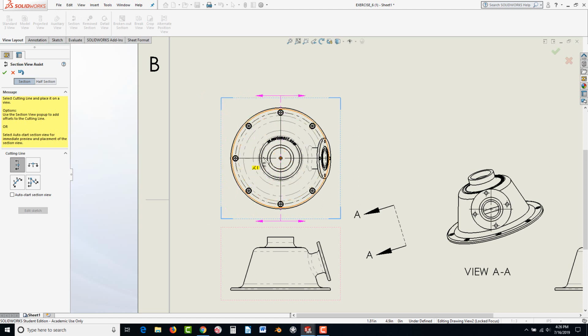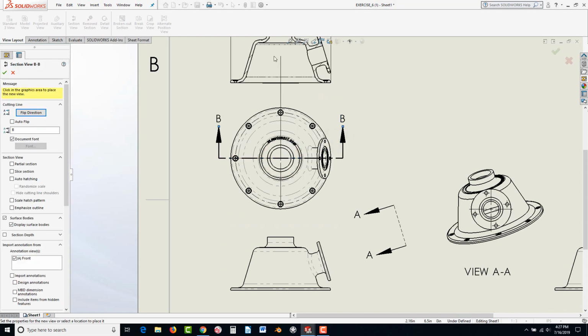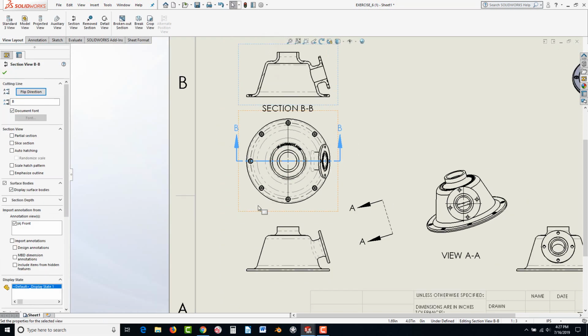But look at this, our arrows are vertical. Let's change that. Over here on the left, you have the ability to go with horizontal. Notice there's some additional advanced ones, aligned and auxiliary, but let's go with horizontal and get to the dead center of that and click to release it and hit the green check, and now move your pointer up and click to drop it up there.